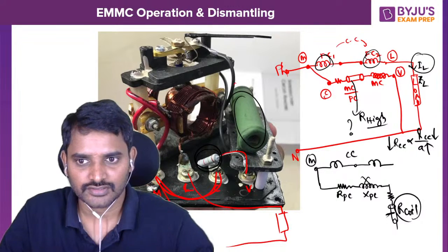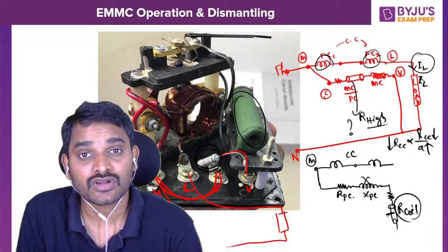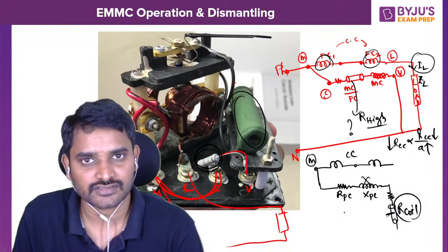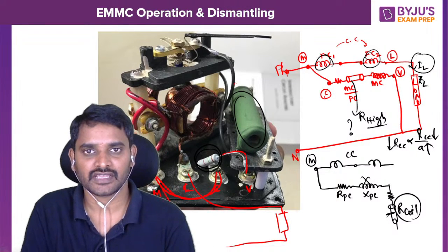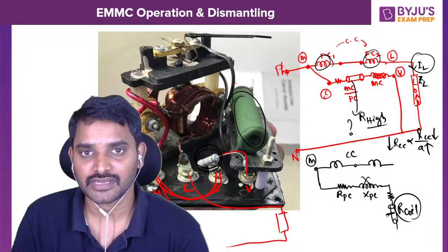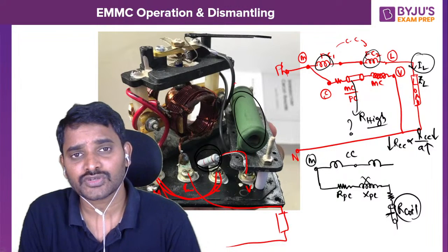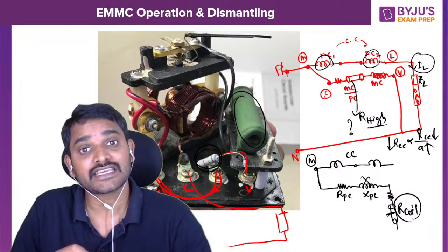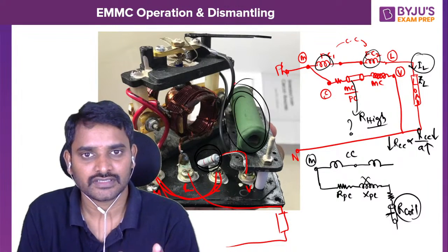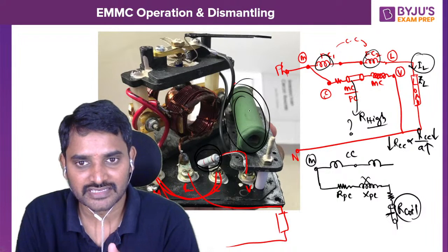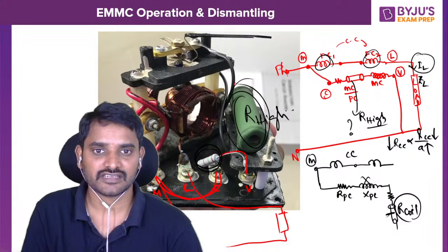To dominate the inductive reactance, and that's why we say the pressure coil of a wattmeter is made highly resistive, so that the error due to inductive reactance can be minimized. So that's the point. Still, if you want to eliminate the error due to inductive reactance, we will keep a capacitor. But in this instrument, we do not have a capacitor at all in this range. Okay, this is not a capacitor, this is a high value resistor. Keep that in mind.